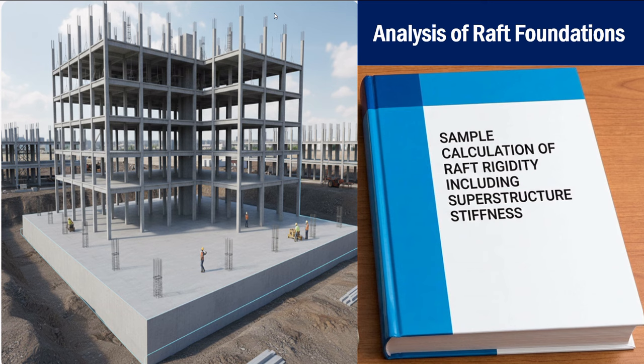Here I will showcase a sample calculation report to help you understand the procedure for the evaluation of overall rigidity of Raft plus superstructure system. This information is crucial in classifying the Raft as flexible or rigid for final analysis and design. I am very optimistic that this topic would be relevant for both structural as well as geotechnical engineers.